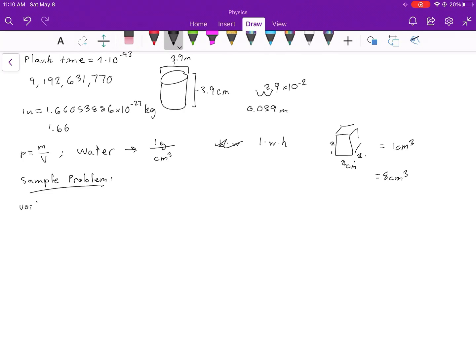And the possibility of liquefaction in sandy ground can be predicted in terms of the void ratio. The void ratio is also known as e, and e is equal to V voids over V grains. V grains is the total volume of sand grains in the sample, and V voids is the total volume between the grains. If e exceeds 0.8, liquefaction can occur during an earthquake. So if V voids is great enough relative to V grains, over 0.8 in the ratio, then you would be able to sink in it, kind of like water.